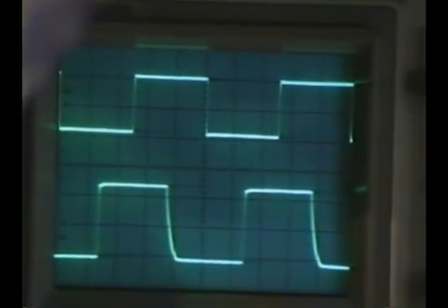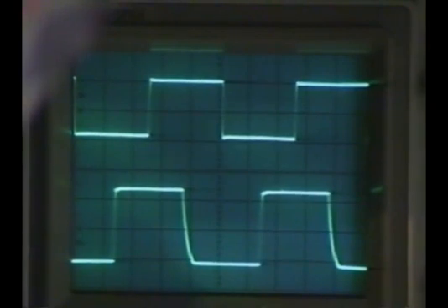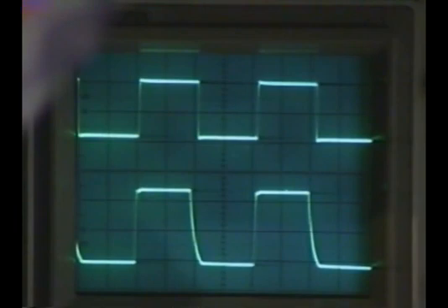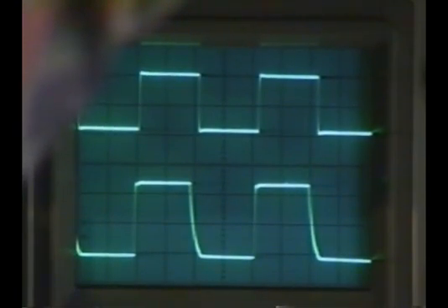And what I can do now is increase the frequency here, or decrease it. So let's increase it like that. And you can see easily that it's quite synced. They're quite synchronized. In fact, whenever you see a pretty picture like that, they're synchronized. Now, check out the phase. What's the phase difference between the two now? Well, okay, 0 is good, but maybe it's a bit positive, right? What does that suggest is about to happen? We're about to run off the end of our phase detector, right? In fact, I'm even surprised we got this far, to tell you the truth.